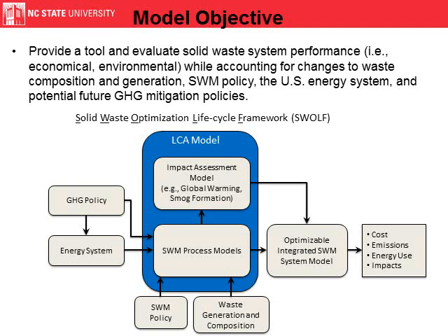All of this input data needs to be developed and can then be input into solid waste management process models, which we'll discuss further in the presentation. But solid waste management process models are these life cycle inventory models for all of the processes in the solid waste management system, from collection to landfills to recycling to composting to anaerobic digestion. These inventory models then develop coefficients that can be used in an impact assessment model to calculate global warming potential or smog formation or eutrophication or ecotoxicity.